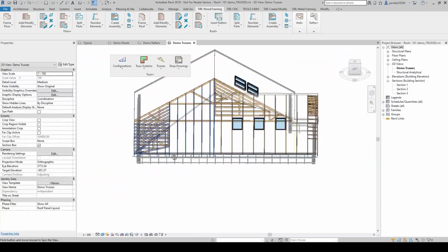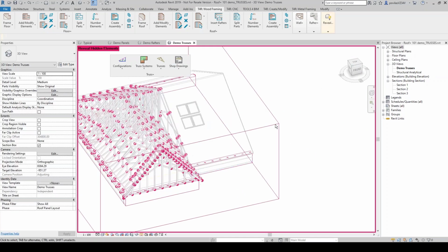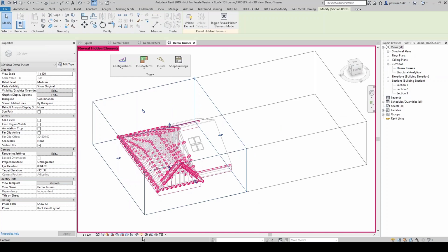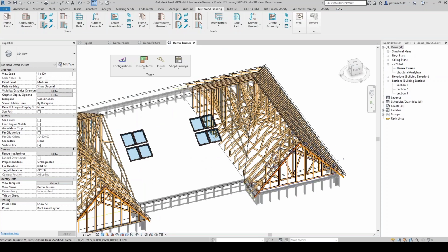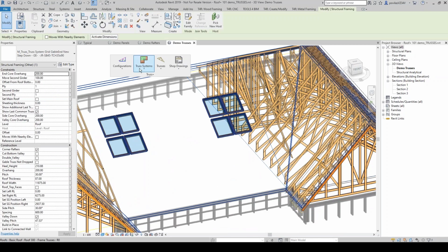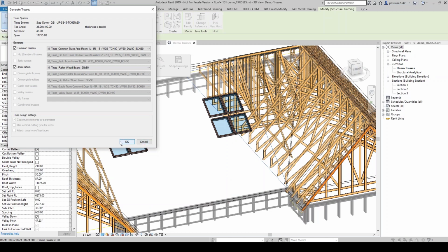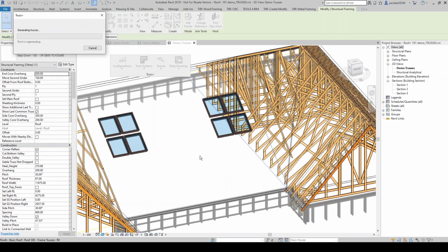Okay, so if I just expand my scope box to the other side, where I have already framed those trusses to be exactly the same. Okay, and we're just missing this bigger truss here. And once that's done, I'm going to show you how you can array trusses between two existing trusses.